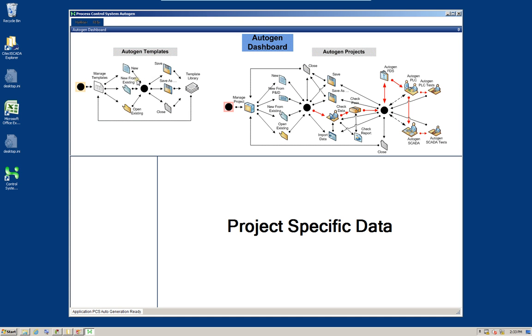In general, that's a text tag descriptor, which has the tag name represented by a placeholder for the tag, the tag type, and a comment or tag description. The auto generation process would take this tag descriptor and replace the tag placeholder with a real tag for the control system, taken from the design input data entered by the engineer for the particular control systems project.